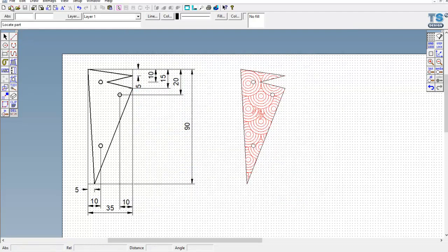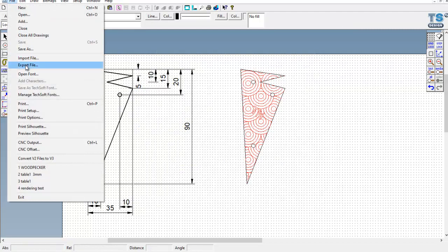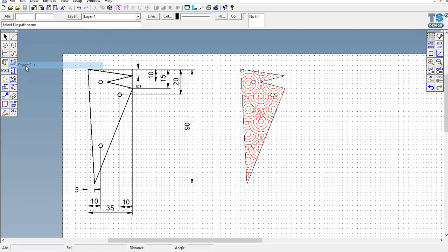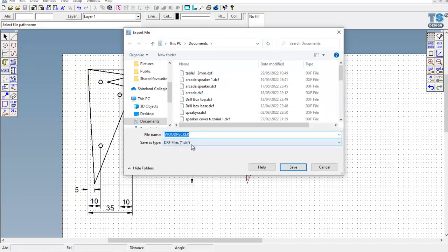And then on this part, if I then go to File, and then this time I need to click onto Export, and you'll see that it will automatically change it to a DXF file, a data exchange file. And you can just make sure that your name and your form, so for example it could be John Smith 7.1, that you place into there, and that can be emailed then across to myself, and we can then get this laser cut out for you. Or alternatively, it's easy for you to find and to send it to us so we can laser cut it out from that point of view. And that's it really, and that's the basics for using Techsoft version 3.